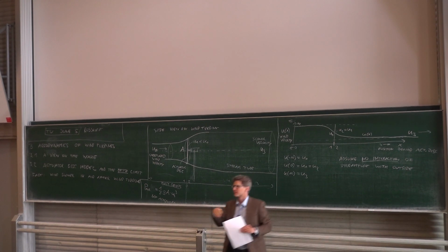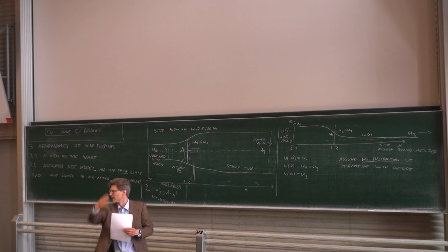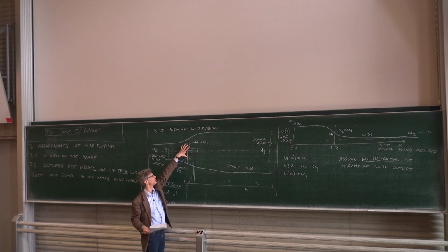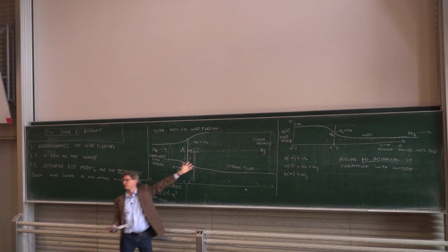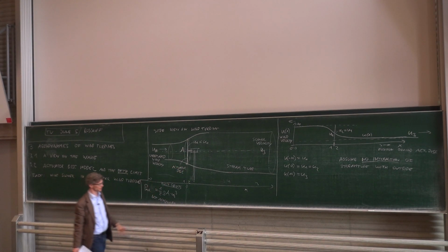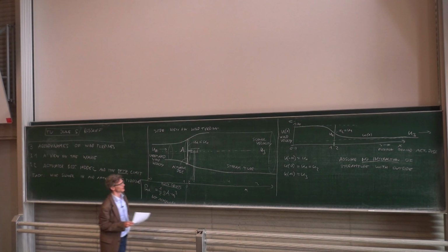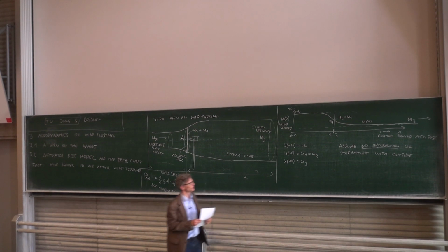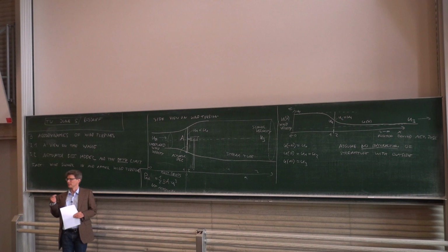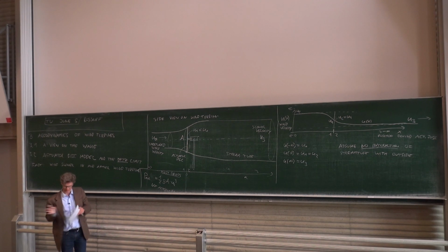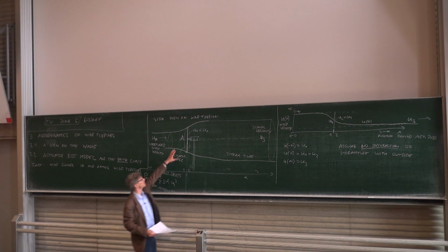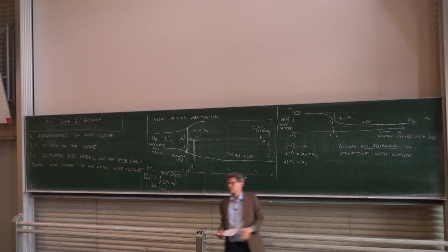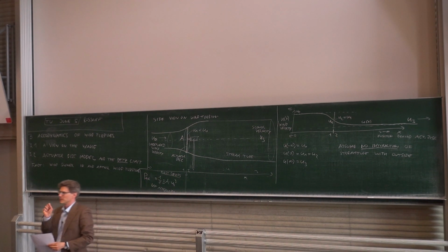And this reflects reality, of course, not to infinity, but to a really large value. Usually you measure it in times the diameter, and if you go 3-4 diameters down, you will have a very close approximation of what we will have here. So this is the first thing that I wanted to give as an idea. And of course, the velocity is something that you cannot abruptly change. Even with a disk, there's air flowing through it. So we can safely assume that this u1 and u2 are the same. This will not be the case for the pressure, and that's why I introduced 1 and 2 as different numbers.